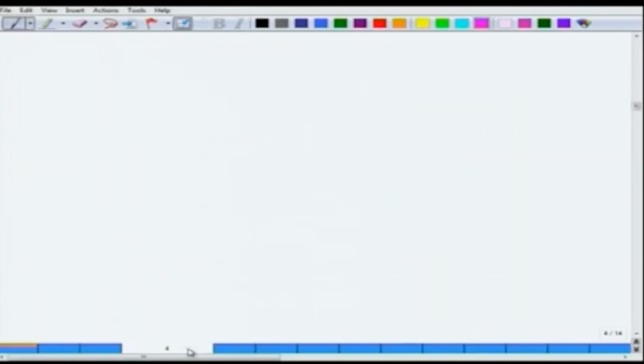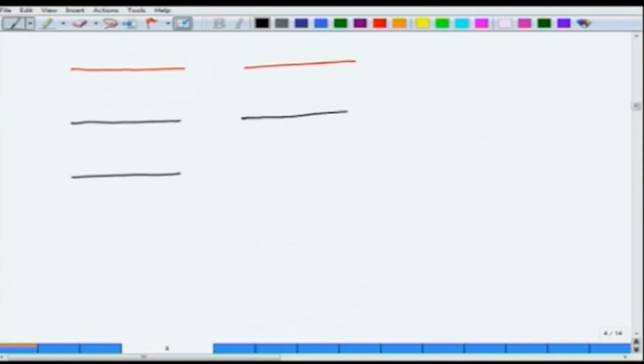So, what I am going to do is, let us take two materials, one is right here, this is the vacuum level, and this is the other material. Let us draw conduction band, valence band, conduction band, valence band of the other material. So, this is EC, this is EV, and let us call it material 1, this is EC2, conduction band of material 2, this is the valence band of material 2, and this is the vacuum level.